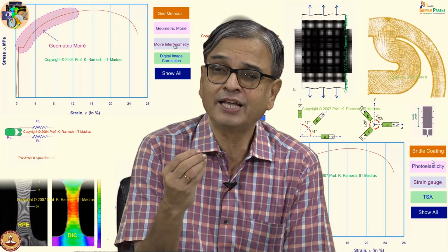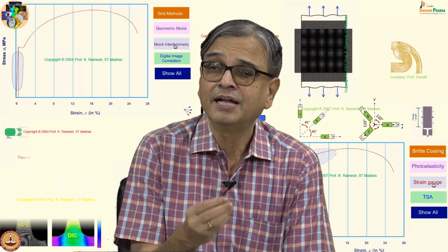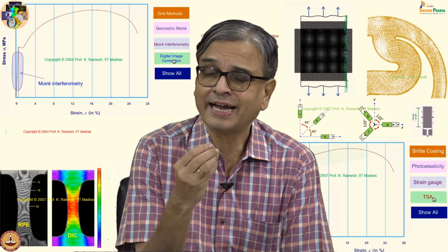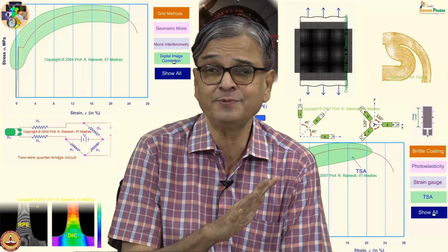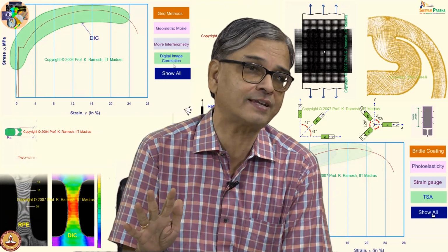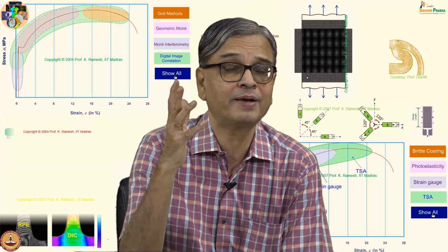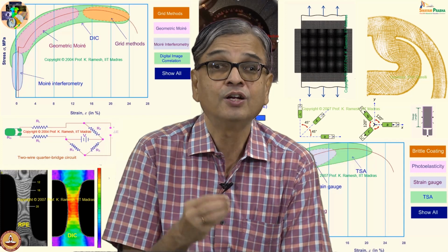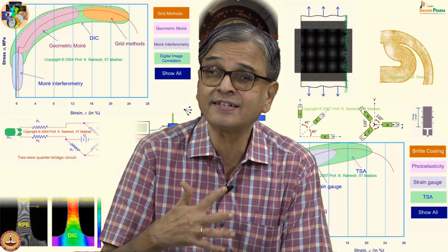And when I use it as a transducer, my focus is to measure the weight accurately. So, in order to get the signal properly, I would like to amplify the signal. There is a difference between strain measurement and a transducer application. In a strain measurement scenario, even if the strain is small, my strain gauge should be able to give me the value. In a transducer application, in order to improve the accuracy, I would like to maximize the signal.